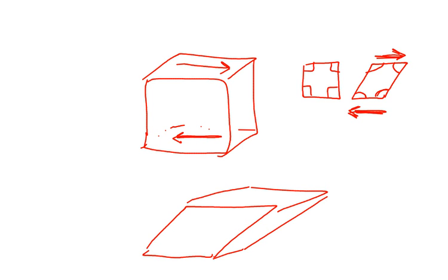And what you're going to see later on, and I'll keep pointing this out, is I always suggest to students that when you're trying to tell whether a part is going to be under normal stress or under shear stress, you draw a square on the side of your part, and then you try and imagine what shape that square deforms into.